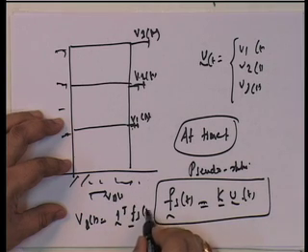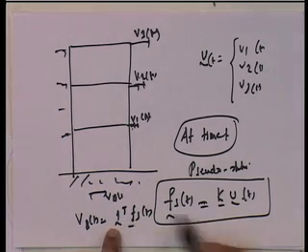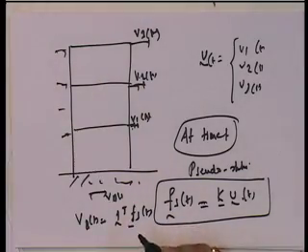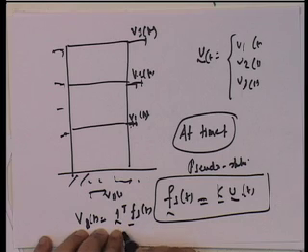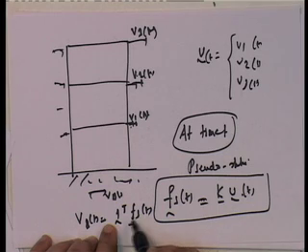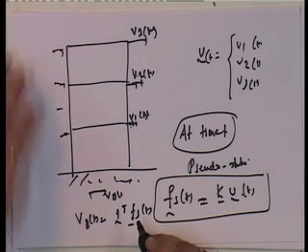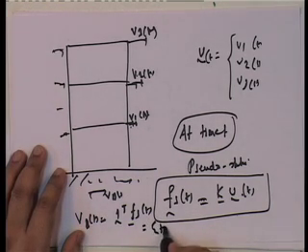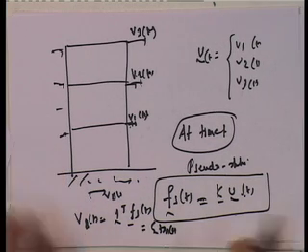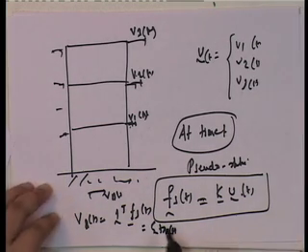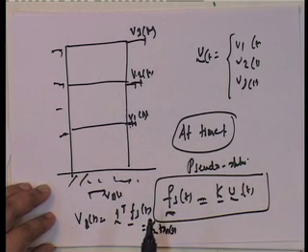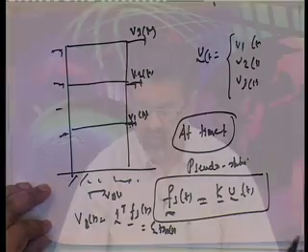I can write V b of t as, note, if I write 1 transpose, this is a vector of 1s, 1 1 1, so it is a 3 degree of freedom, 1 1 1, into Fs. So, look at this, 1 into Fs1 plus 1 into Fs2 plus 1 into Fs3, which is nothing but a summation of this. This is equal to summation of Fsn. So, understand, once I get Fs of t, for that load I can find out all the force responses that I need to find out. So, Fs is equal to k into V.